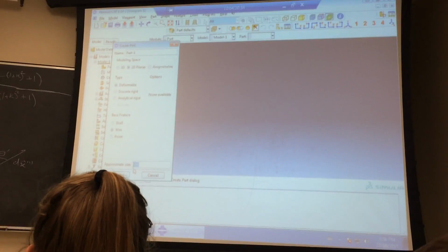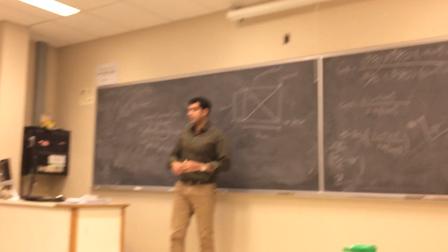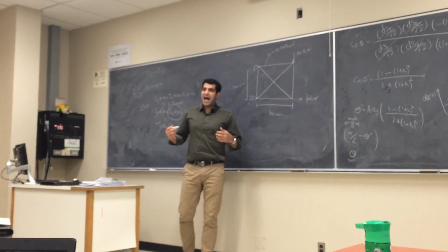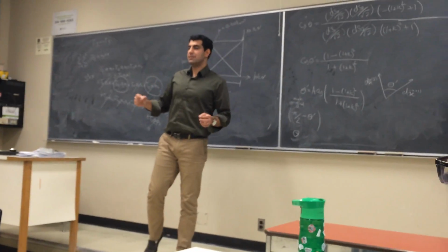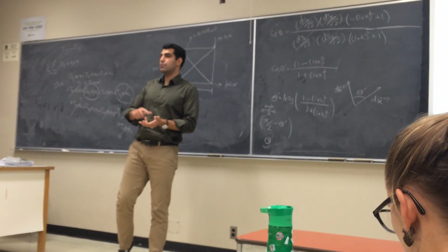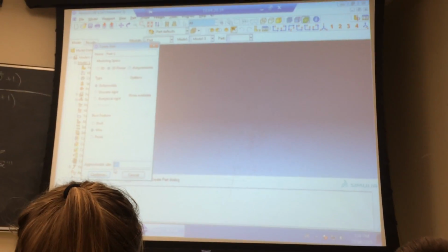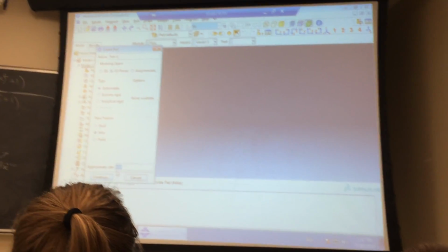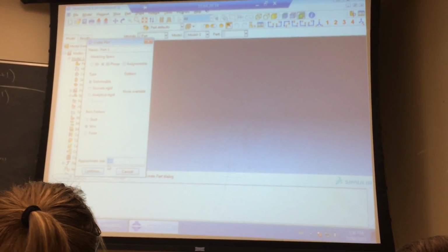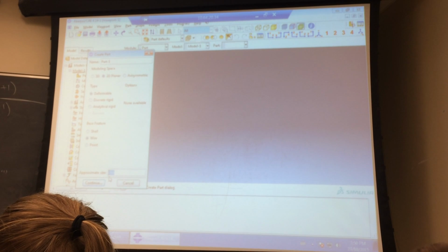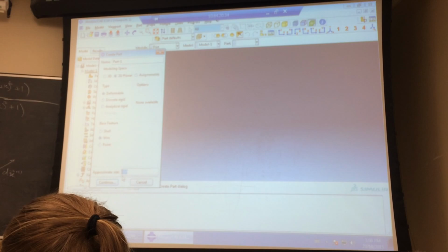So for the units, some of you asked me a question about the unit that you're going to use. Abaqus does not ask you about the exact unit. So are you using meter, millimeter, or anything? What Abaqus understands is the unit of length. That's up to you guys how to model it. You have to choose a set of units and just stick to it.